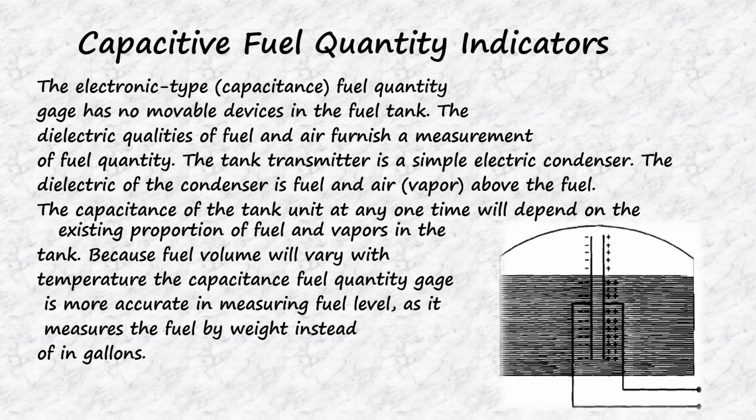Remember that the capacitance of a capacitor is dependent upon the dielectric constant of the dielectric. Fuel and air both act as dielectrics with different dielectric constants. As the fuel-air ratio changes, the average dielectric constant of the mixture changes, affecting the capacitance of the capacitor. The fuel quantity indicating gauge reflects those changes in capacitance.